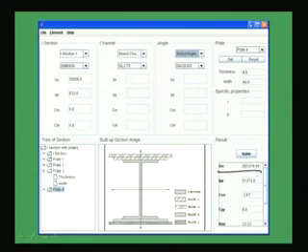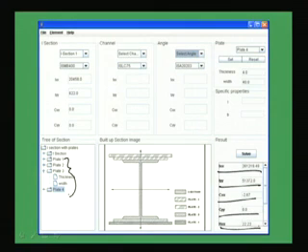That is the equivalent IXX, equivalent IYY, CXX, CYY, RXX, like this we will get RYY and cross sectional area, all the things we will be getting, where different plate thickness has been given for different plates. So in this way very quickly we can find out the equivalent properties of the built up section. This is the advantage of using such software, where the user can find out the required equivalent properties of the built up sections at a moment.